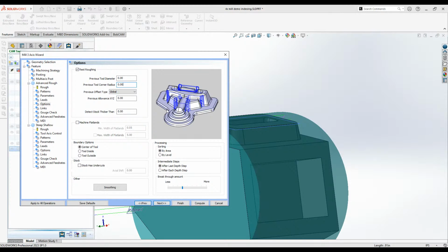Say for example, from my experience with customers, they will have one programmer and they will have it machined with a certain tooling that they have designed, and then if they want to go back to the SolidWorks part file here, for example, they can use a new tool based on the previous tooling that they've used, and then calculate just the tool path that they need for this specific tool after the fact, basically.